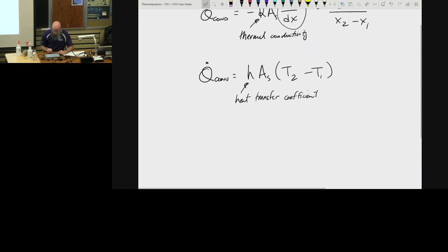But we are going to change down here when we have Q dot radiation. It is going to be epsilon, which is going to be the emissivity, a number between 0 and 1. How do you know if you're going to use that equation if we neglect radiation or include radiation? Does the problem statement give me emissivity? You can't look that up. It has to be given to you. Okay? Sigma is the Stefan-Boltzmann constant. It's given to you on your equation sheet.